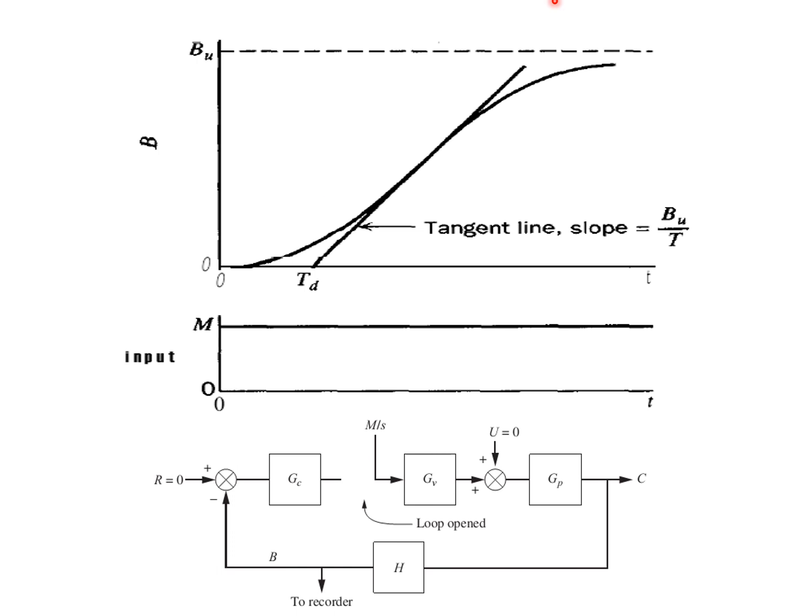Okay, you can see here, this is what you did just now, the open loop test. You're supposed to get the response here from the measurement recorder. Normally you should get a process reaction curve response, a sigmoidal sort of response. So what you do, you draw a tangent at the inflection point, as close as possible. A slight difference is not a big issue.